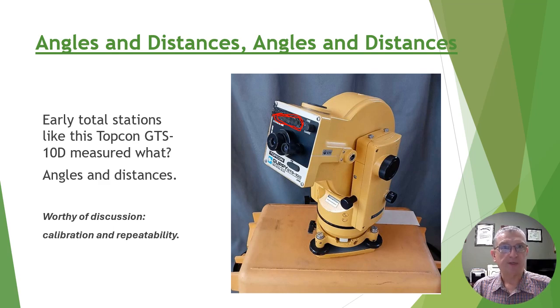There's also the repeatability side, because everybody knew that with a calibrated steel tape, even if you made corrections for heat expansion, you could repeat that distance. You could take two different people, take another calibrated steel tape, go measure that distance correctly, and it was repeatable. There was no doubt that was 250.47 feet long or whatever.